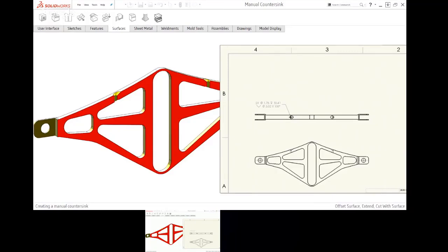The routing tool that's in SolidWorks Premium, the question is how do we do cables and wires? The routing tool basically uses sweeps along a 3D sketch. So behind the scenes, you give it a couple of connection points and it creates a 3D spline, or in the case of rigid piping, it creates an orthogonal type of path with some built-in rules, like for wire bend radii, pipe bends, and things like that. But it's essentially a 3D sweep.